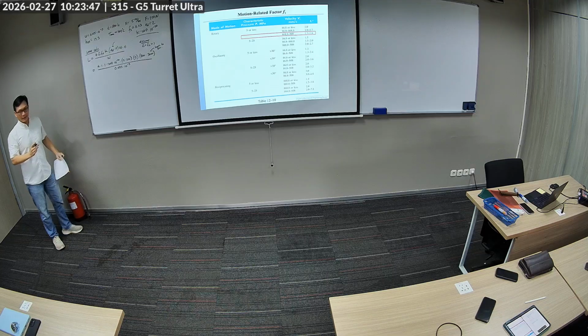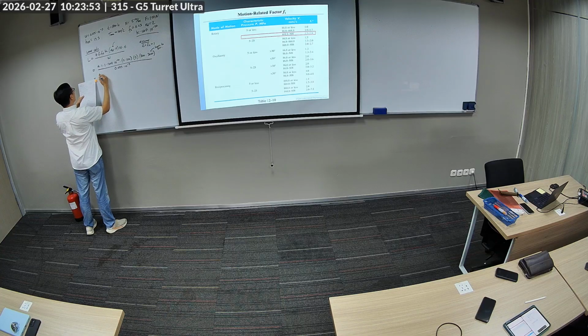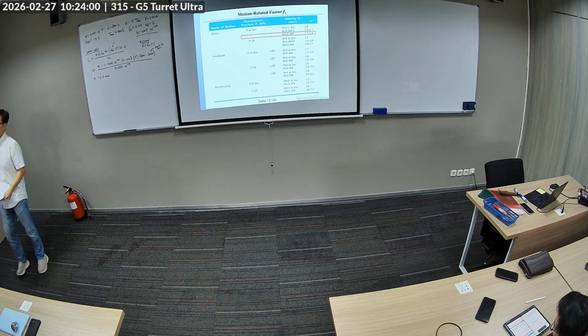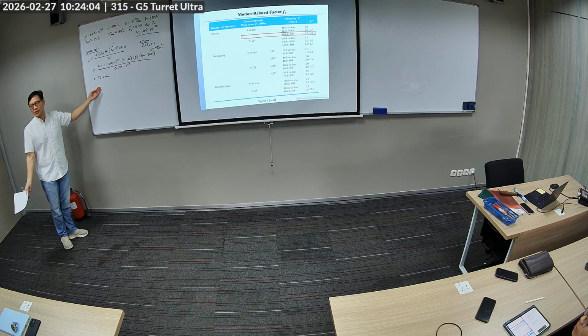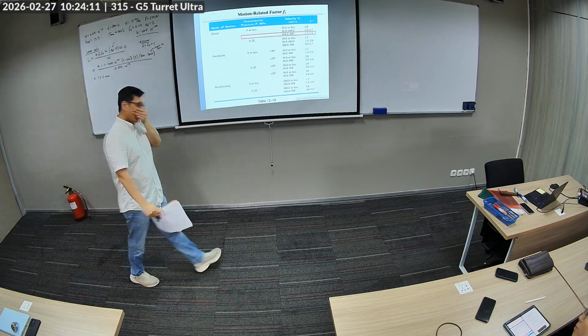Okay? So following? Yes. Okay. So this ends up at 12.2 millimeters. First of all, this is theoretical, right? So there is no bushing with 12.2 millimeter length. I mean, you're gonna round it up to the next available one.